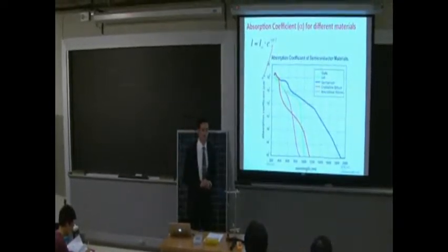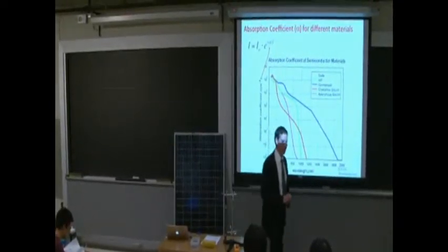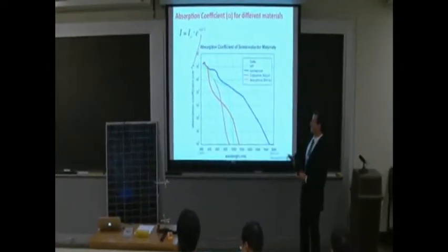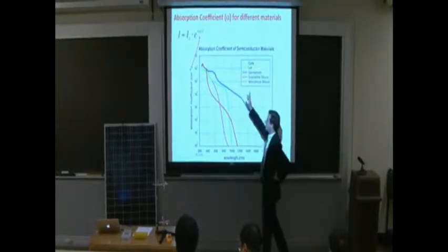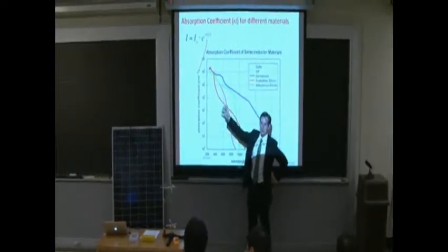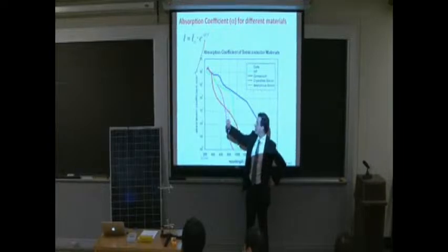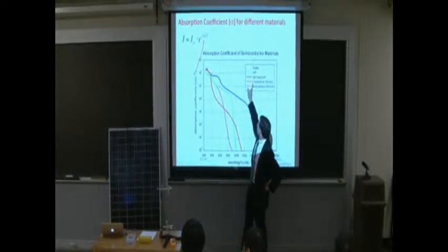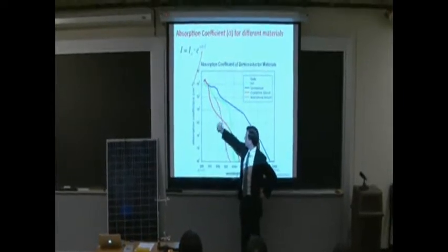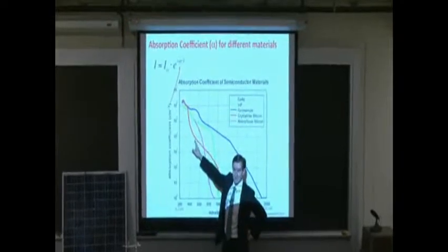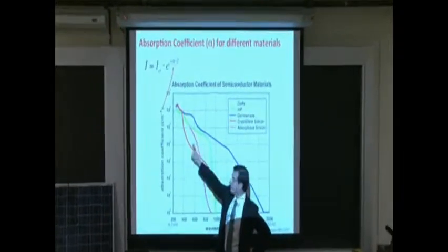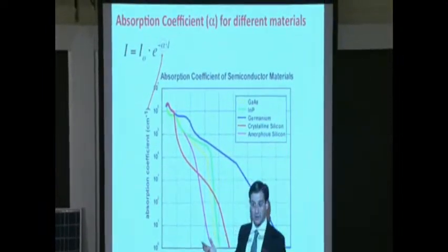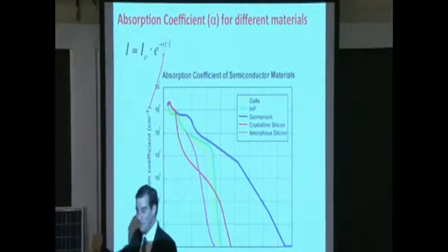Why don't we give folks enough time to walk through? I know I rushed you on the calculations here. We have material to get through, and I wanted to see it perform under pressure. But how about the silicon? Is it larger or smaller? Let's just go for order of magnitude first, and general trend, and then try to pick up the precise number. For crystalline silicon, with an optical absorption coefficient an order of magnitude less than gallium arsenide, is the thickness needed to absorb the same amount of light going to be greater or smaller? Greater. By an order of magnitude. Brilliant.